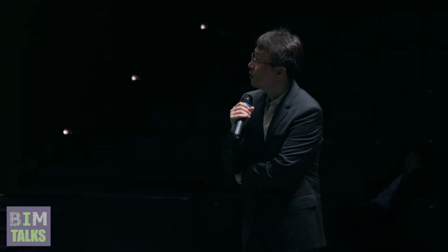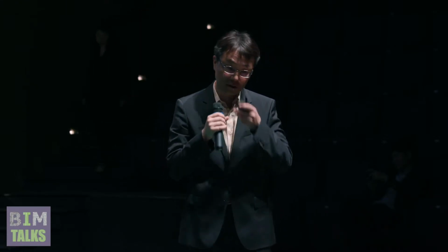So I'm interested in investigating and developing methods to fully automatically construct a geometry model from images, and then develop a method to identify semantic information between those identified building objects, and then create valid models at LOD 100 or 200. Particularly, I'm interested in IFC-based BIM models, which is Industry Foundation Classes. It's an international standard.